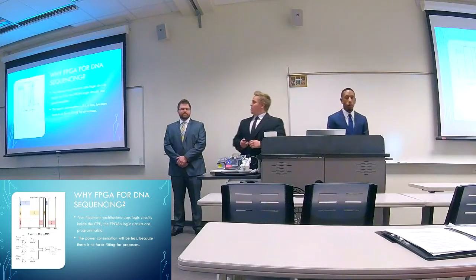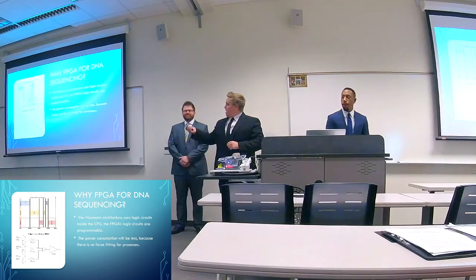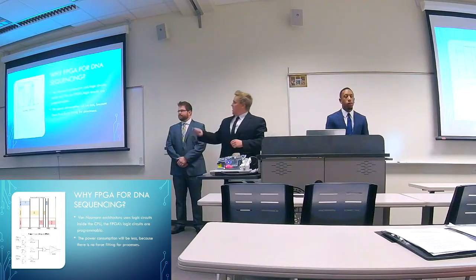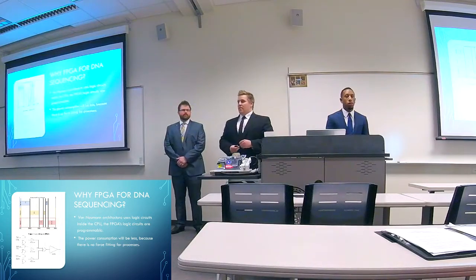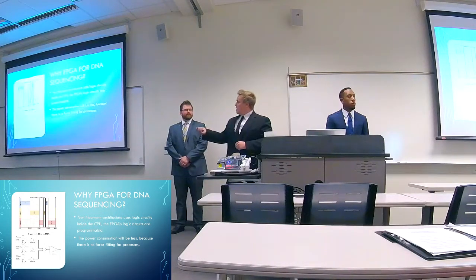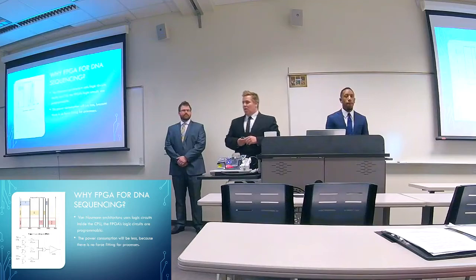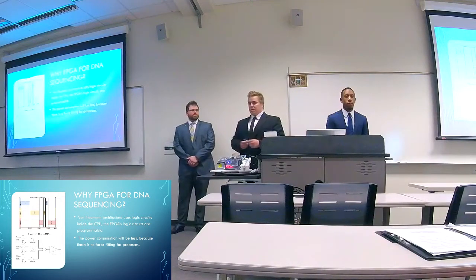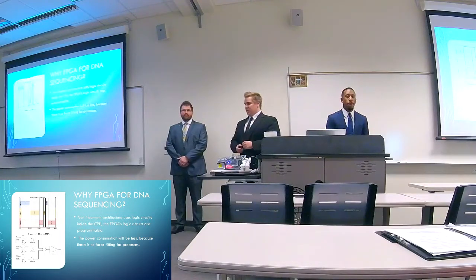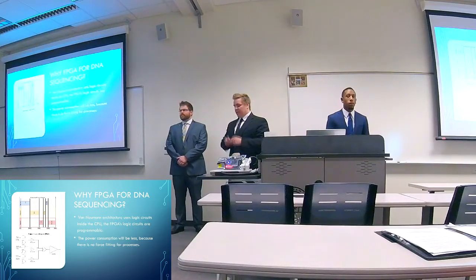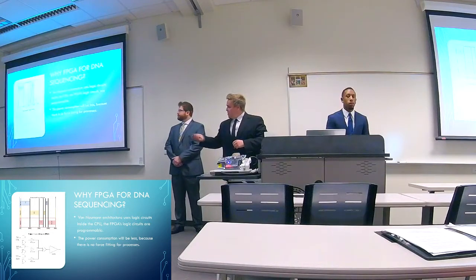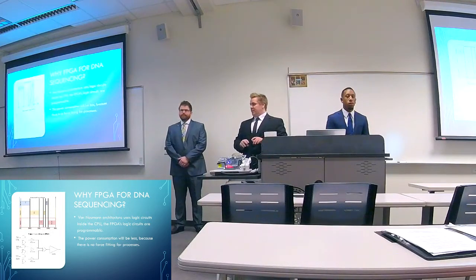So as I said before, with von Neumann architecture, you have a typical fetch, decode, and operation cycle. So imagine this blue line here is Google Chrome, and yellow is like iTunes or something like that. So you have a fetch cycle, and in order for that to keep going and have something else run with it, iTunes needs to fetch its instructions as well. Then they need to decode and operate. So these time delays are small, but it's kind of gymnastics to get the circuits to work, and it overall uses more clock cycles. So that can be more programming, or that can be more power intensive. Whereas an FPGA is a bunch of logic circuits that you build through programming syntax like Verilog and VHDL to perform certain tasks. So there's no force fitting for this process.